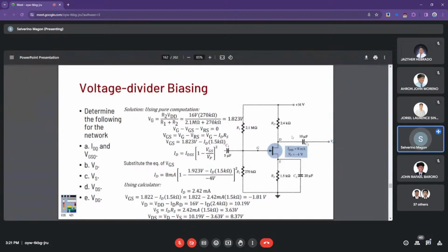In AC analysis, what is viewed from the output as the reference or maximum voltage swing that you can utilize is this VDS value. Because in AC, you're going to bypass this source resistance again. So essentially in AC analysis, this is nothing.